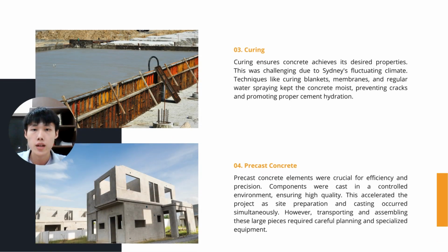Third will be curing. Curing ensures concrete achieves its desired properties. This was challenging due to Sydney's fluctuating climate. Techniques like curing blankets, membranes, and regular water spraying keep the concrete moist, preventing cracks and promoting proper cement hydration. And fourth will be precast concrete.